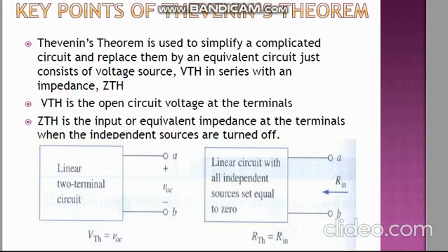So students, now I will discuss Thevenin's theorem. That is pretty important while calculating some sources and some impedances, to make them a single source and single impedance. So Thevenin's theorem is used to simplify a complicated circuit and replace it by an equivalent circuit that just consists of a voltage source and an impedance.